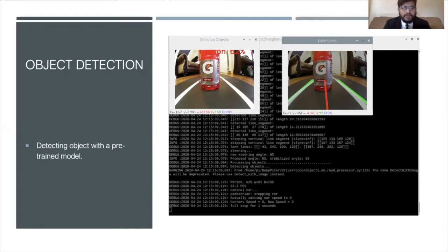I have also provided a link in my report to a web service provided by the Google Coral.ai team, where you can put in your original pre-trained model and it gets converted into the .tflite file and the quantized format which is needed for the Edge TPU.